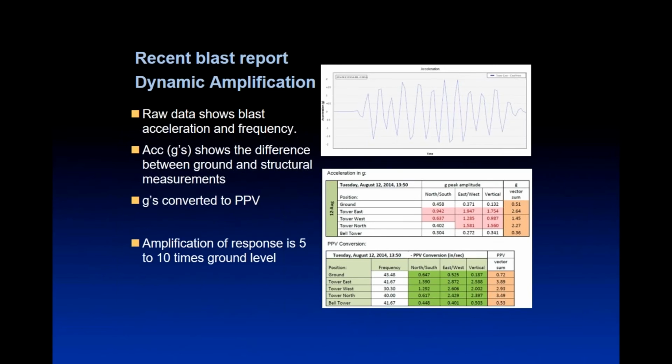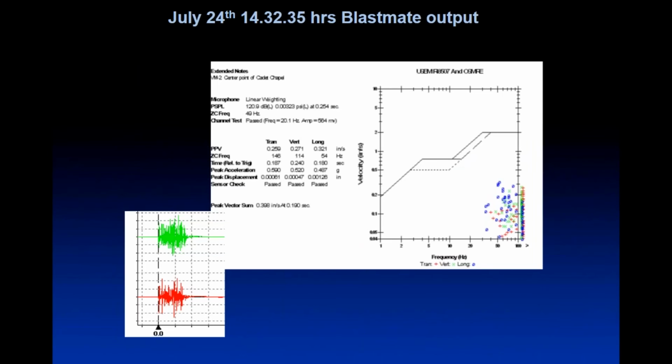This was a study of blasting near a church in New York State. We measured by acceleration 1.8 Gs peak to peak at 33 hertz, impinging on the structure. The waves came through the ground, and we had the Doppler effect because it wasn't straight onto the building.